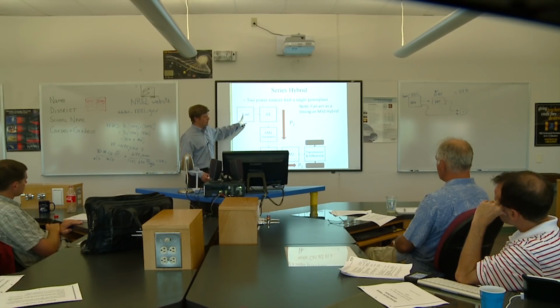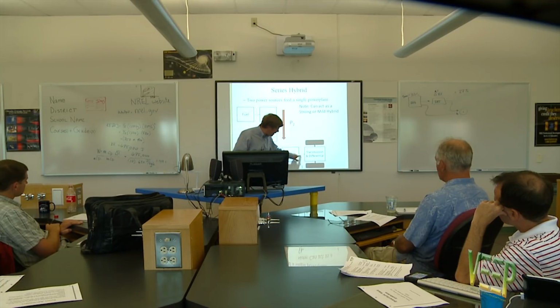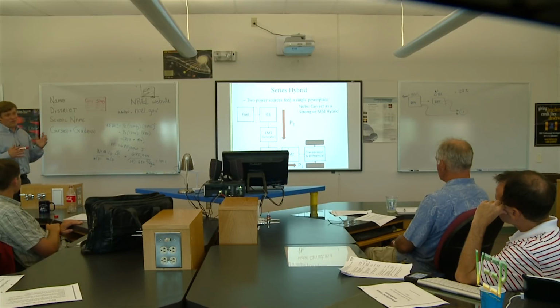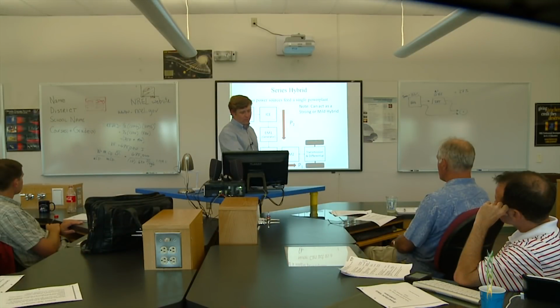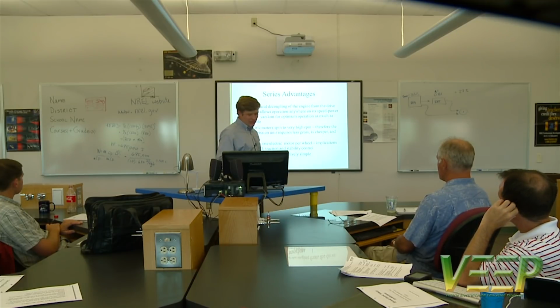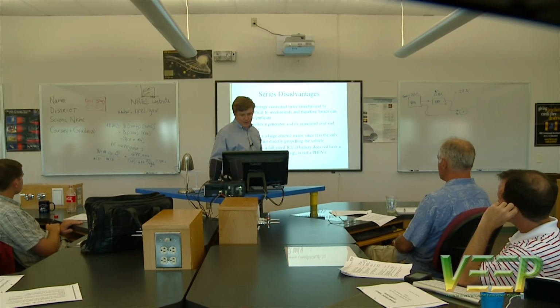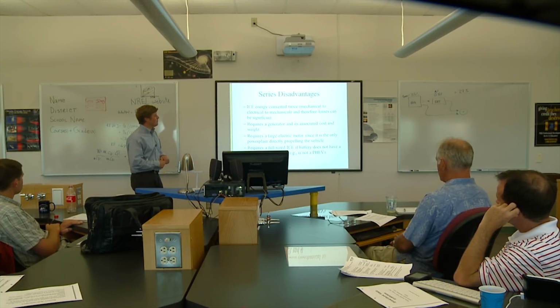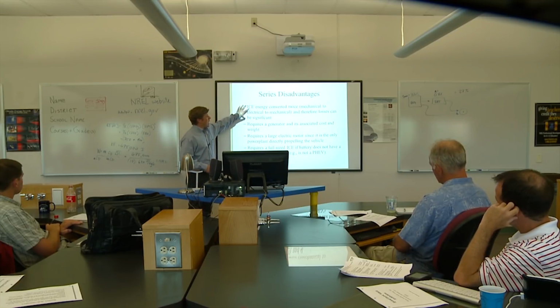It's a conversion from chemical energy to mechanical energy, from mechanical to electrical, from electrical to chemical, to electrical to mechanical and out again, right? Depending on the mode of operation, there might be 3 to 5 different energy conversion efficiencies that get tacked onto what we would conventionally think of as just a chemical to mechanical energy conversion, right? So the losses can be significant here.